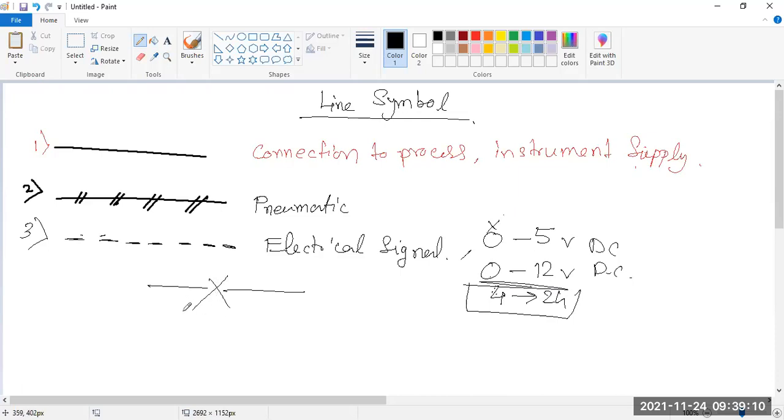If the signal is 0, it also means no signal. So how can a controller understand which one has happened? That's why this 0 is called dead voltage, and we use 4 volt or 5 volt as the 0 signal. Okay,